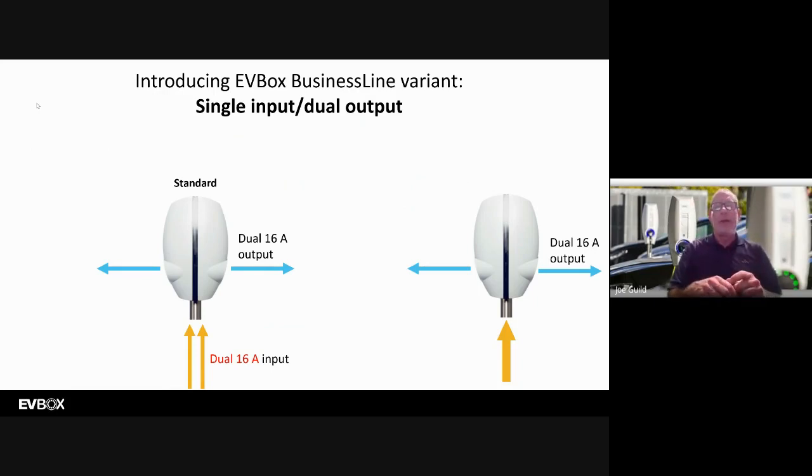That's very simple. But we do have a version of this which allows you to use 1 cable. But that cable, of course, has to be 32 amps, not 16, because I need 16 on both sides. But inside this station, we secure it at 32. And then we split it to the different sides so that it's safely done. The one on the left, if you try to put the 1 cable on the one on the left, it's not going to work. And worse than that, it might work, but it also might not work, and then you'll be confused. So a lot of people make these confusions.